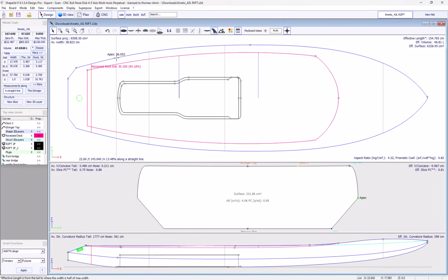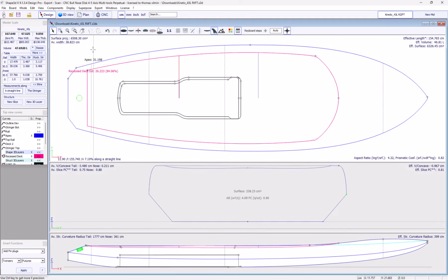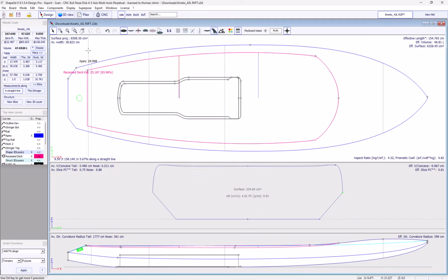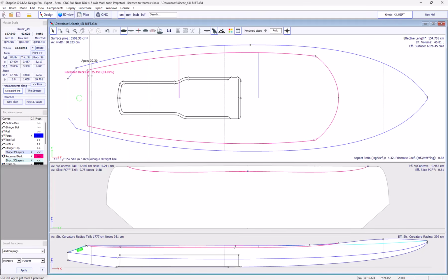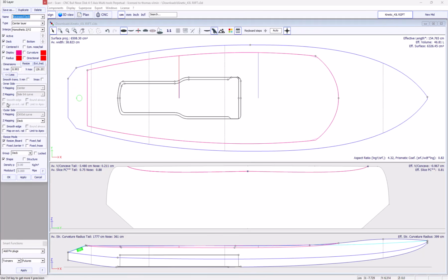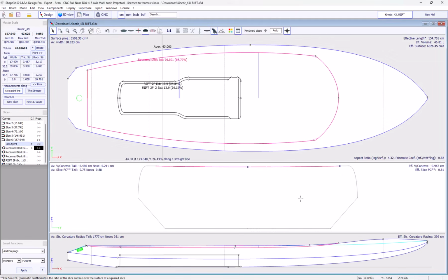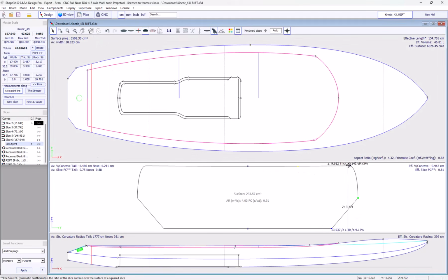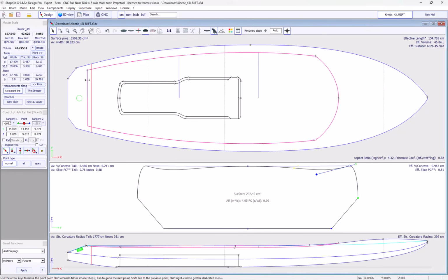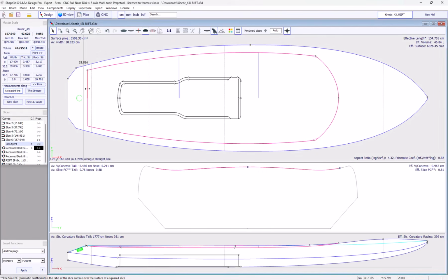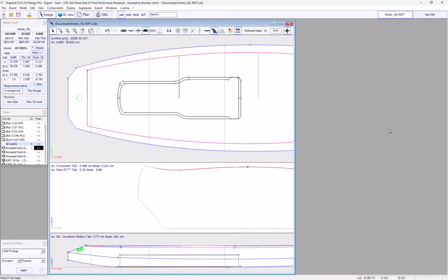Another new feature we have for the 3D layer is to have continuity at the tail or nose of a 3D layer. For example, if I look at this recess deck, if I go towards the tail, then there is a step here. And if I want to correct the step, I need to insert a slice here on the 3D layer and adjust it. But now you can just use the function smooth transition for xmin position here, and it has inserted a slice here that is exactly copying the original shape. And even if I move the shape of the board, then automatically the tail slice of the 3D layer will copy this shape to make sure there is a smooth transition at the tail.